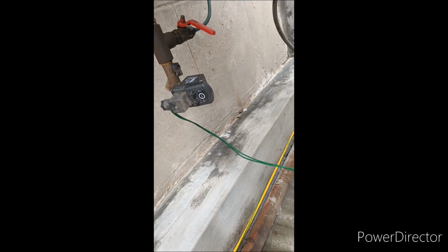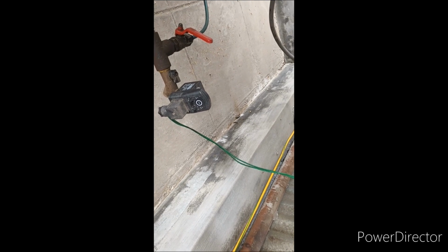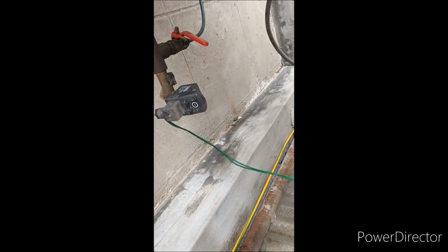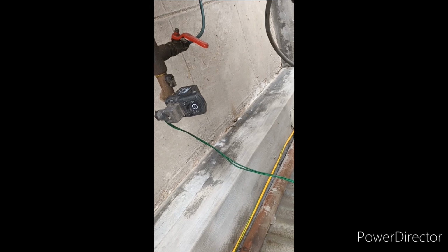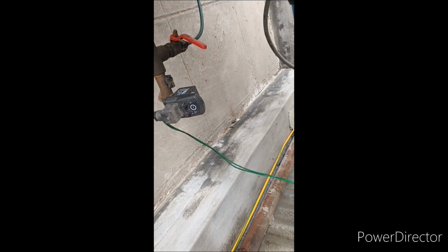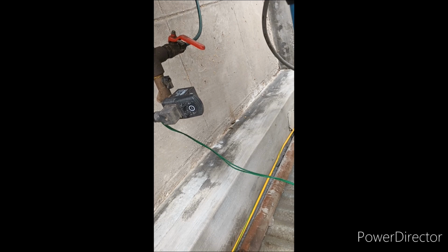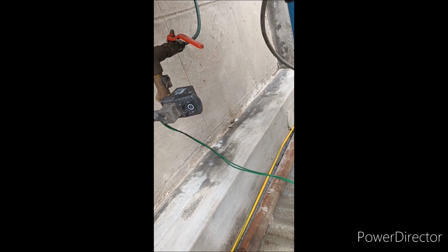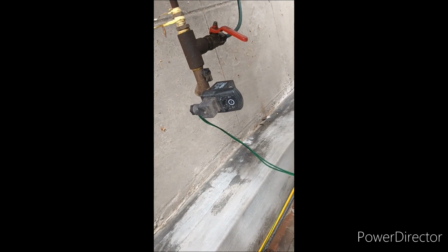After every 24 hours, there is also one more auto drain valve with no loss. That will work like it removes moisture from the air receiver. It will remain on for 5 seconds and remain shut for the rest of the time. It will not allow compressed air to go out from the compressor. So going with the auto drain solenoid valve with timer is very good.